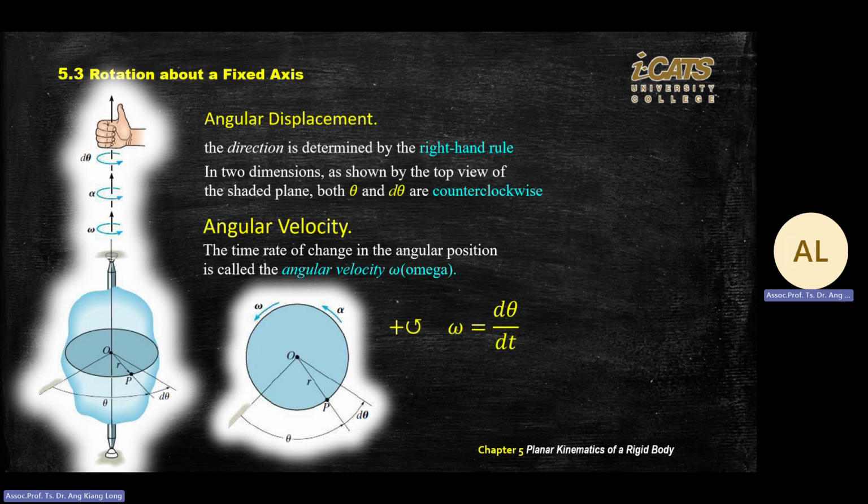So there are two parameters in a rigid body. Position, you get r, you time differentiate, you get velocity, and then you get acceleration. Another one is the angle from the rigid body, you have an angle because of rotation. So rotation you define by angle. With a similar principle, there's a change of angle, you differentiate with respect to time. Theta becomes omega, omega equals d theta dt.